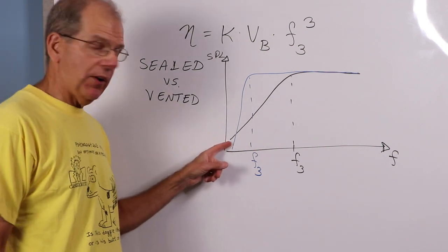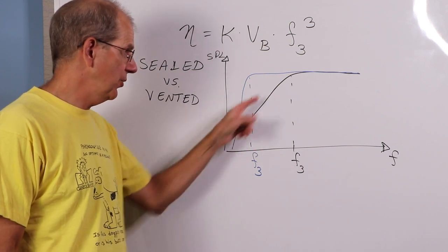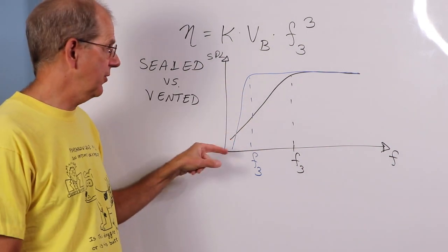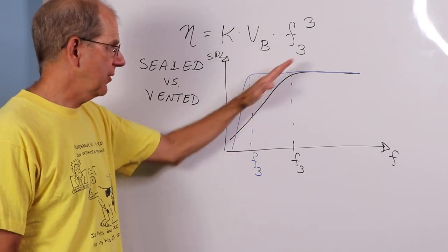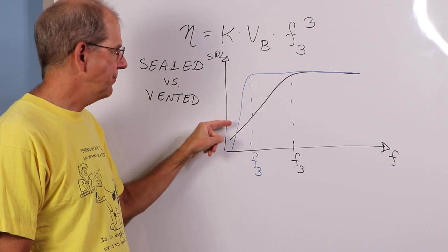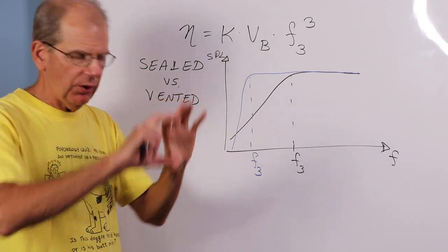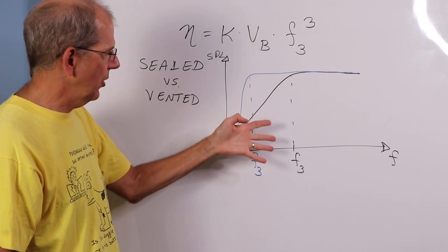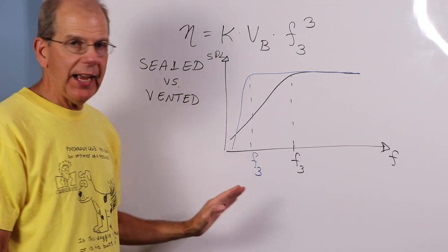And yes, it's true, at very, very low frequencies, you actually get less bass out of the vented system than you do out of the sealed system. This roll-off is faster. On a maximally flat system, this is what we call a fourth-order curve. This is not, okay? You get like a second-order curve or a quasi-third-order curve out of this thing. There's actually a whole bunch of things you can get if you have what's called an augmented system with external equalization. But I'm just going to keep it simple and talk about these two. So you get this extra bass extension, but it does roll off faster.